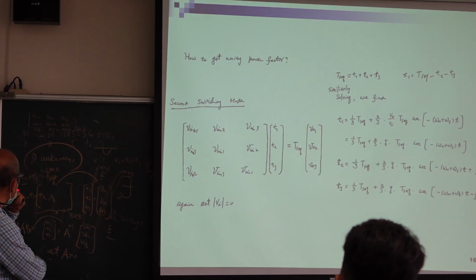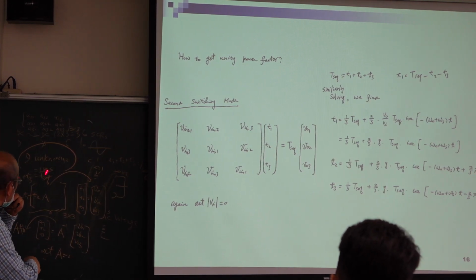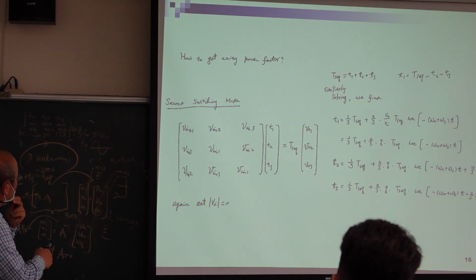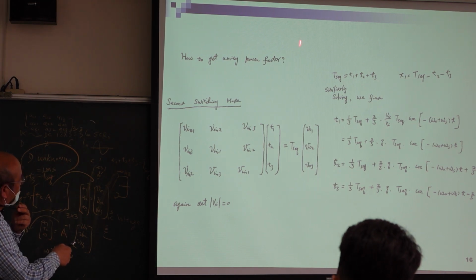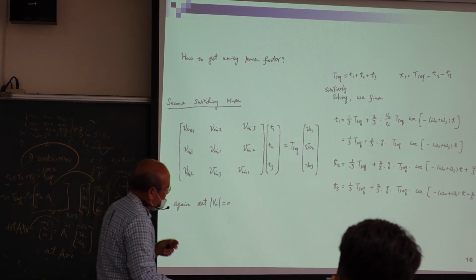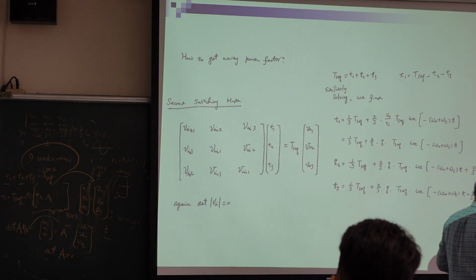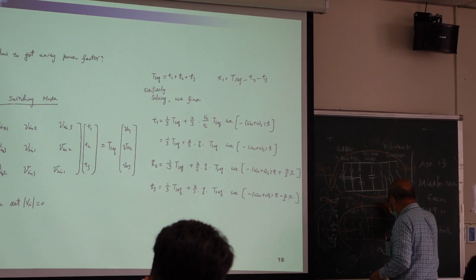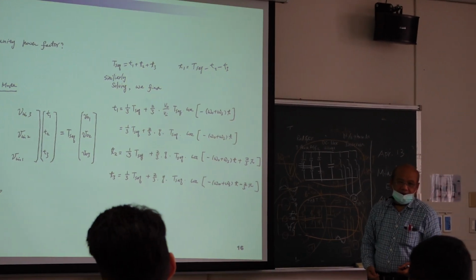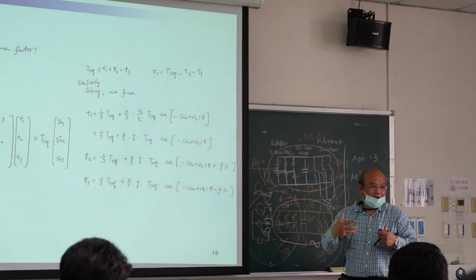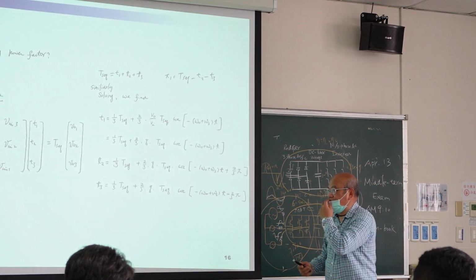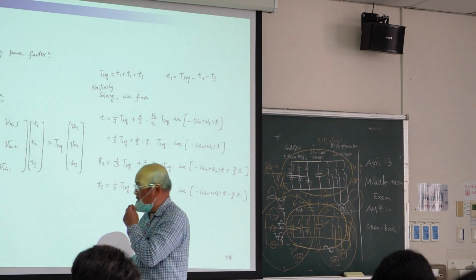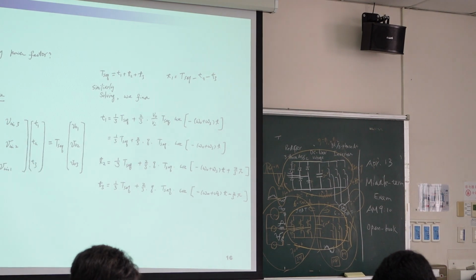We can change the switching frequency, and finally we can obtain 1.0 unity power factor. What do you mean? You mean my matrix converter is equal to this circuit because I can obtain power factor correction, right? This is good because I use 9 switches.